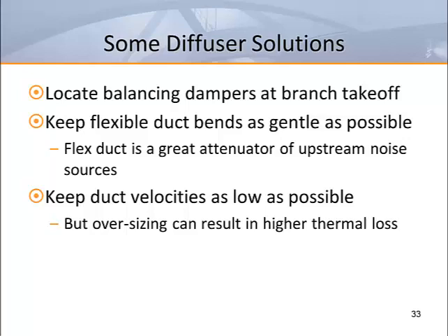Just because manufacturers offer neck-mounted balancing dampers doesn't mean you should use them. A damper on the neck of a diffuser can drastically affect the performance even in a full open position. Balancing dampers should only be located on the neck when there's no other alternative.